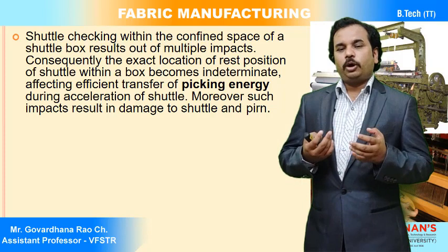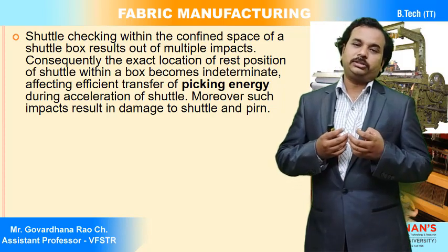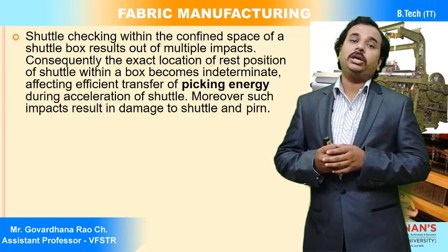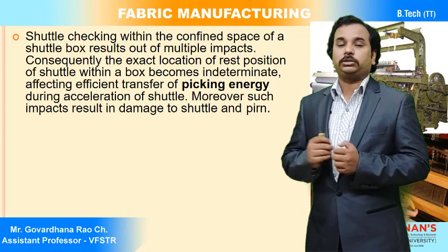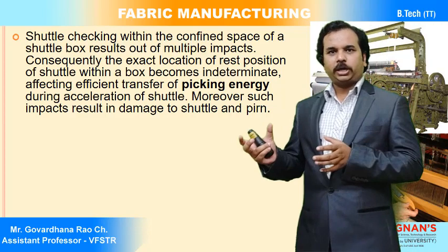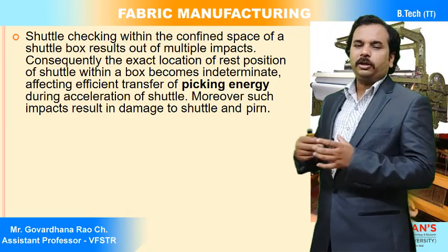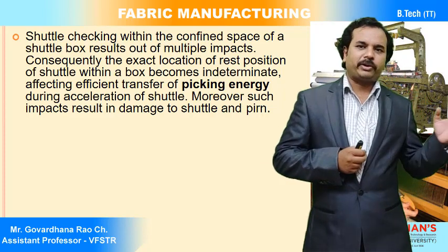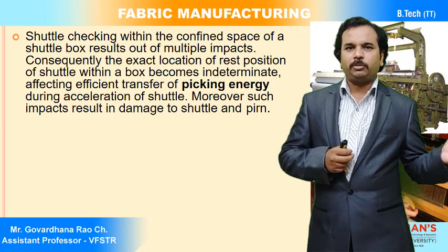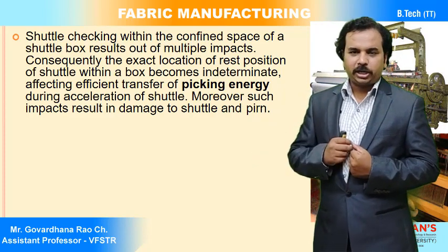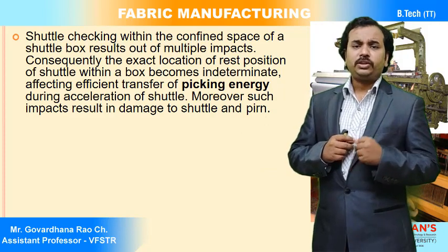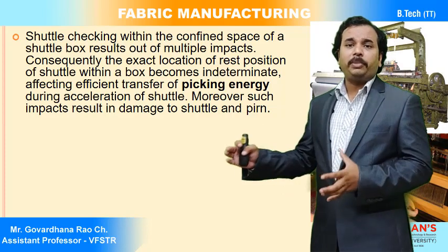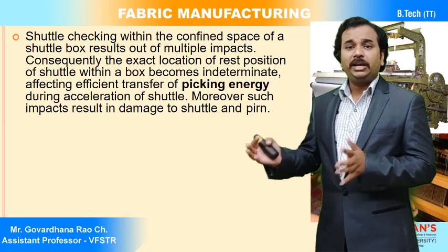There is no idea where exactly the shuttle is going to stop in the shuttle box, because there is no positive mechanism, nothing to hold the shuttle. The shuttle travels from one side of the shuttle box to the other side, so where it will be placed in the shuttle box is not determined.